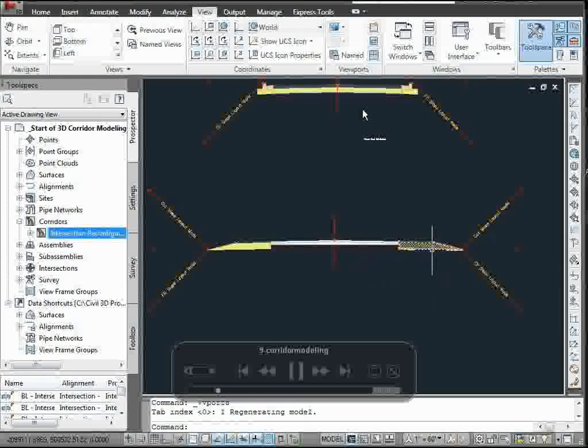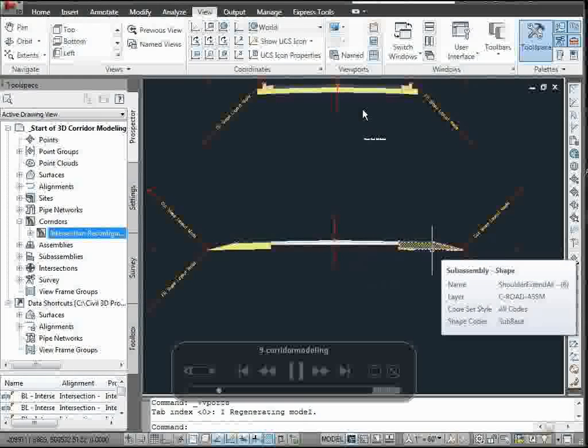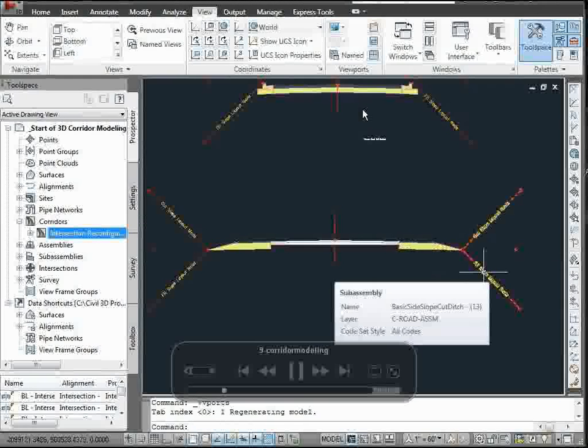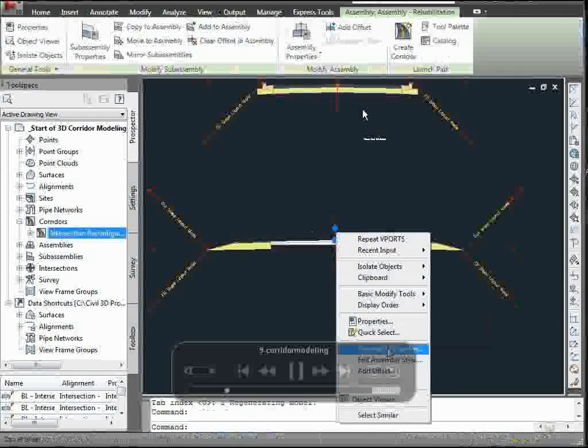You grab them and put them together, but they're also what's called parametric. So as you put them together, they interact, but they also enable you to set different values, like for width and slope and depth and reaction. Do I put a guardrail in based on a height, things like that. These are the concepts that we use to do our corridor modeling.